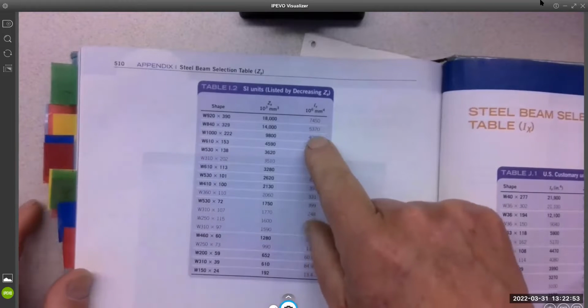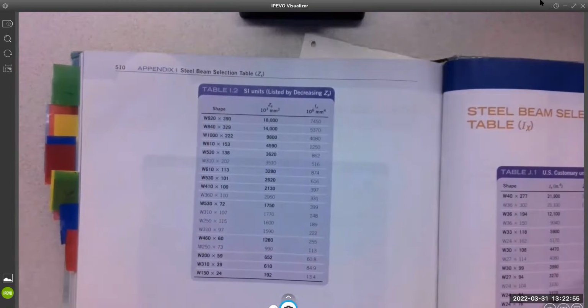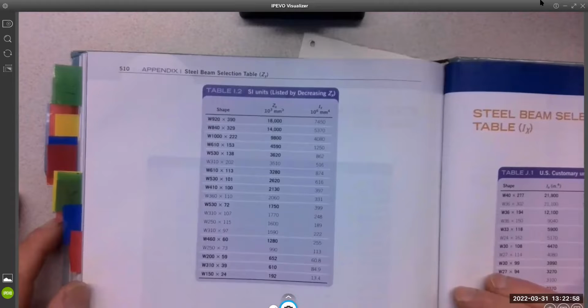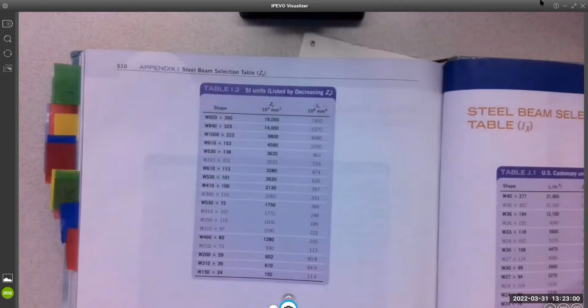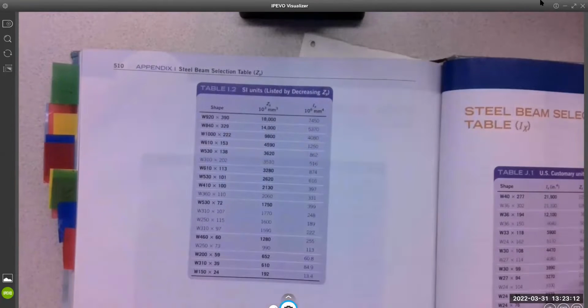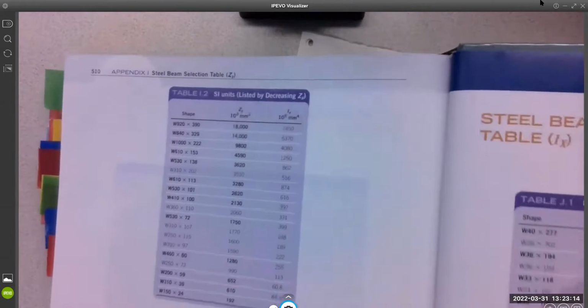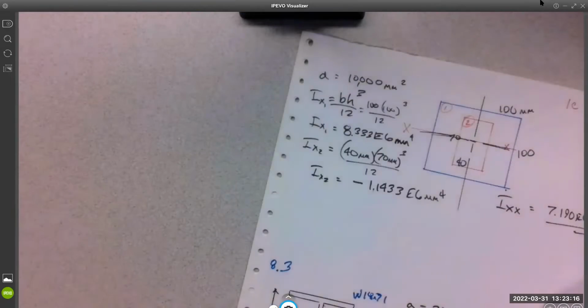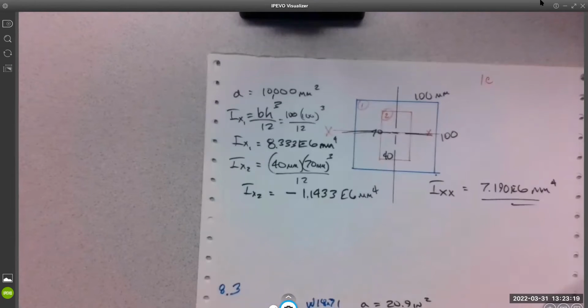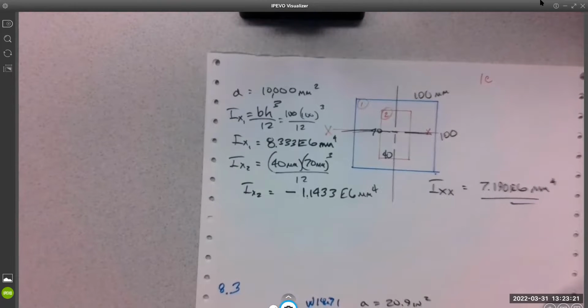Yeah, it's all about the chart you're going to go to. So when you go to work, it could be a different chart. If it comes out of like the American National Standard Steel Institute manual, there are all kinds of crazy units inside there. So you just have to look it up and say, oh, I need that unit because I have to read this chart and see if things work. Inches to the 4th, millimeters to the 4th. But just watch for those 10 to the 6th or 10 to the 3rd factors because that'll mess you up.